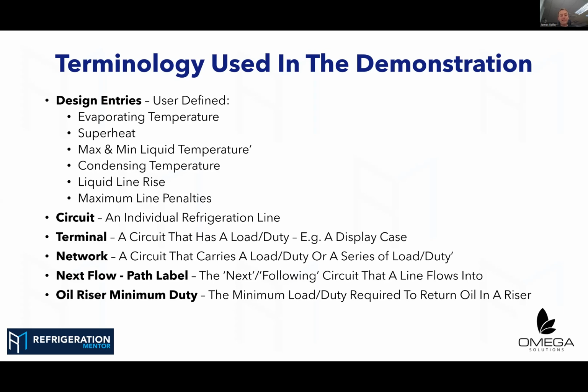If risers are sized incorrectly, especially a large riser or something that's carrying multiple duties, over time technicians are going to get oil faults. Oh, I've got a compressor, or compressors, that have tripped on oil. Technicians assume everything's been designed correctly. So how to clear an oil fault? Well, let's put more oil in the system. Hey, that fault's cleared, on to the next site.